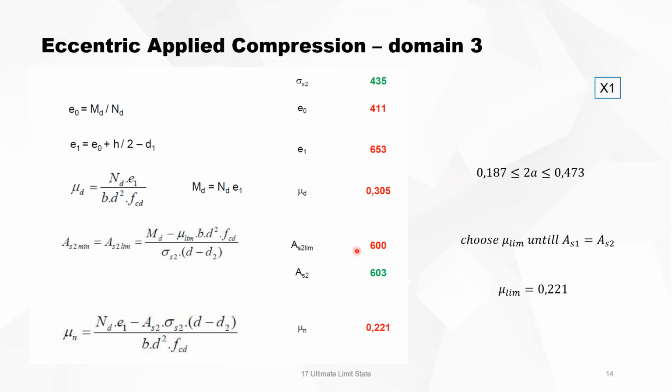Then we calculate the needed reinforcement, but this is now a doubly reinforced section where we assume, in the other cases, that the Chi is 1. We assume a symmetrically reinforced section. So for comparison reasons, we are also going to reinforce it symmetrically. But we don't really need the compressive reinforcement.